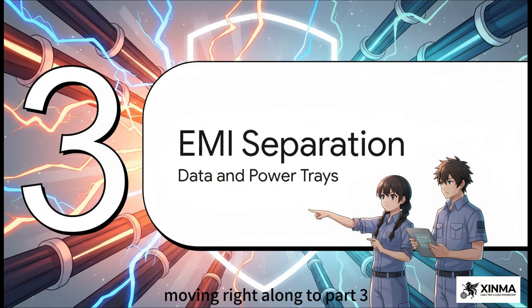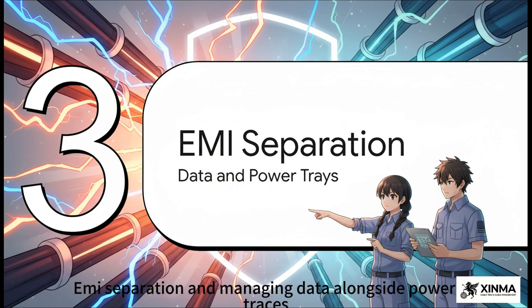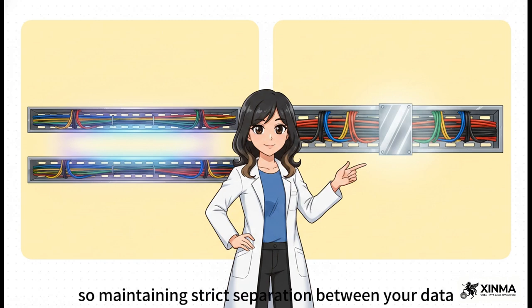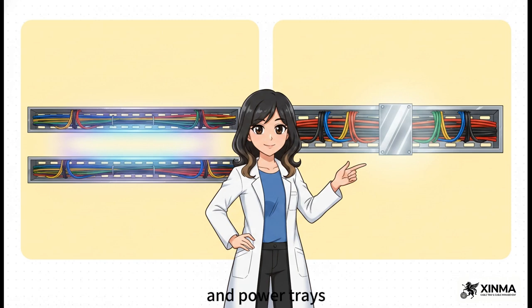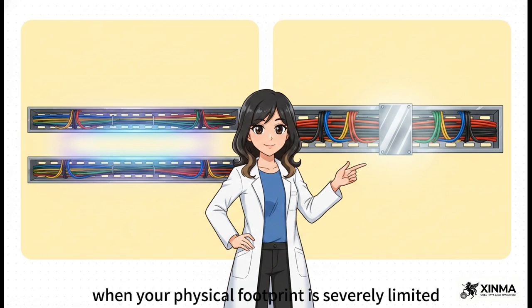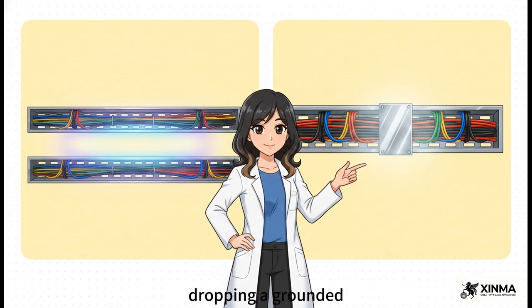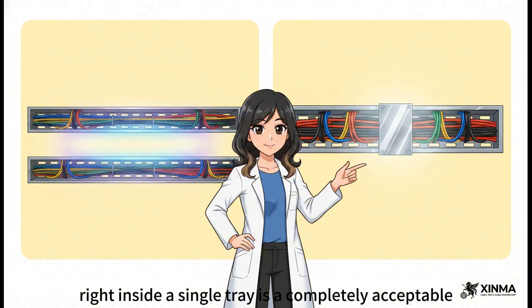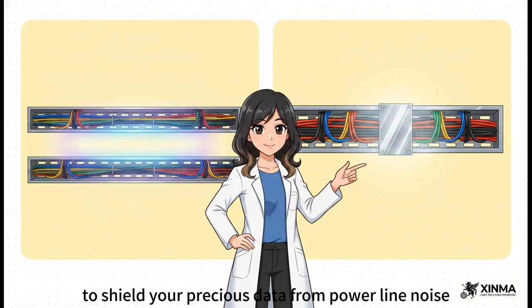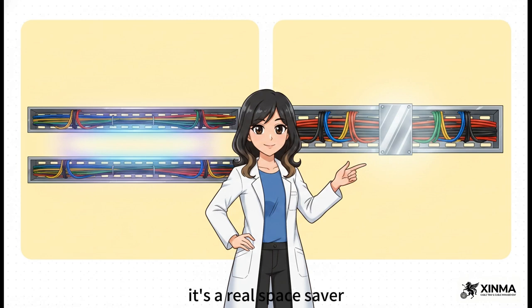Moving right along to Part 3, EMI separation and managing data alongside power trays. Now, physical distance is a fantastic insulator against electromagnetic interference, so maintaining strict separation between your data and power trays, that's the ideal scenario. But let's be real. In actual facilities, space is at an absolute premium. When your physical footprint is severely limited, dropping a grounded metallic divider right inside a single tray is a completely acceptable and highly effective alternative to shield your precious data from power line noise. It's a real space saver.